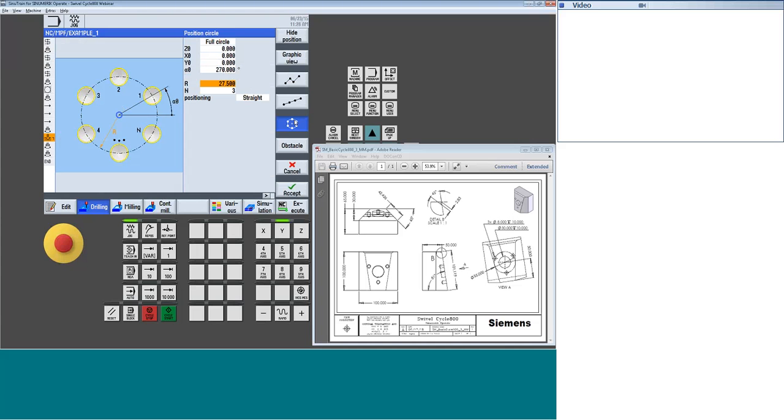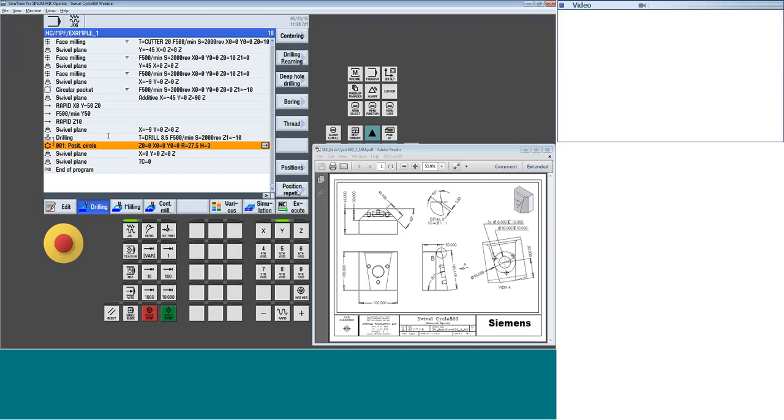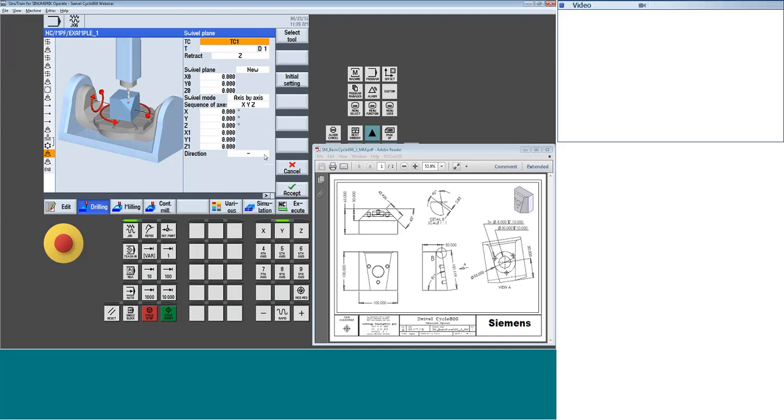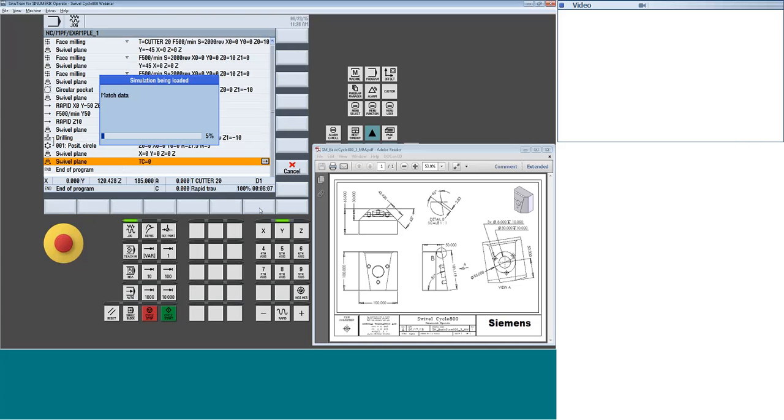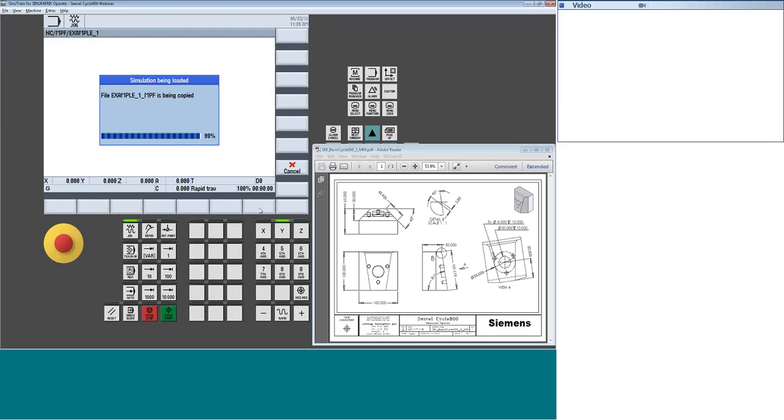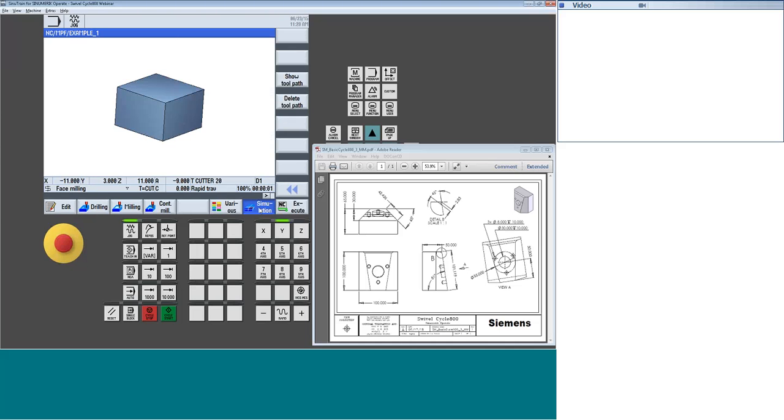So we come down. It does its thing. My shutdown from earlier is still there. So when I'm done, I'm going to retract, square up the table, and shut everything back off. So if I do a final simulation, I should have a complete part. So we come down. We do have an option if you do Control-M. It's a cute little trick. It's going to jump your simulation right up to its max. So shoots it up. There we see we got some drilled holes.